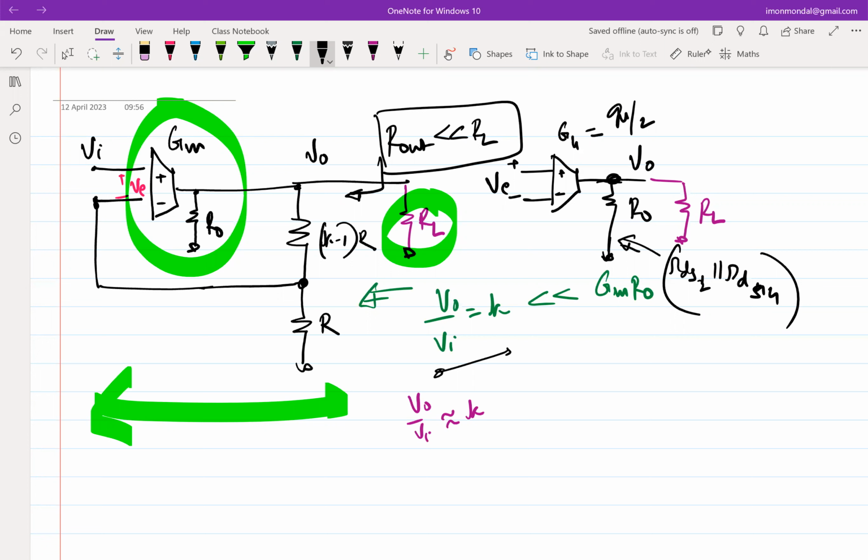So that is correct, but I want to go one step back, in the sense that can you relate the desirable operation of a negative feedback loop with loop gain? What should loop gain be? Very high, very low for the loop to work properly? It should be very high, right? And the good thing about loop gain is it's an open loop thing, right? You don't have to go around the loop.